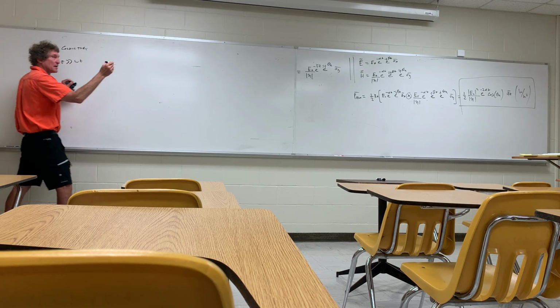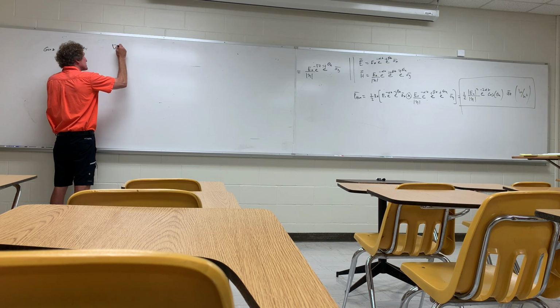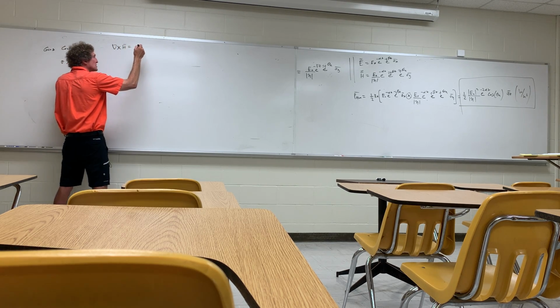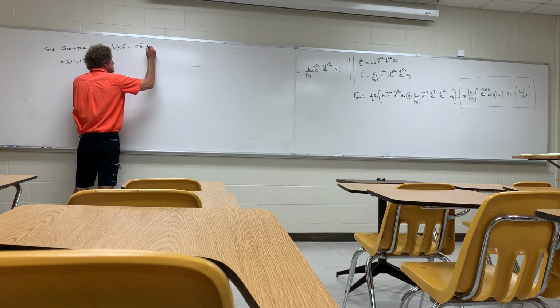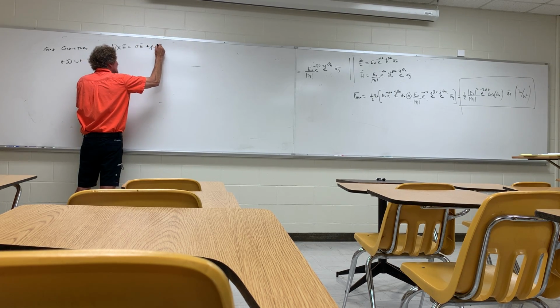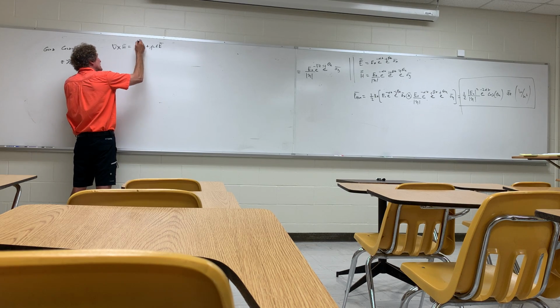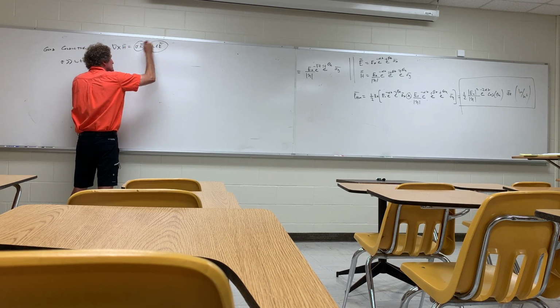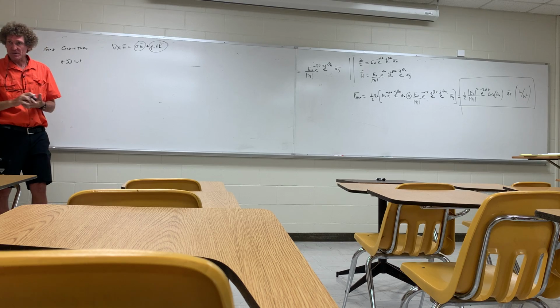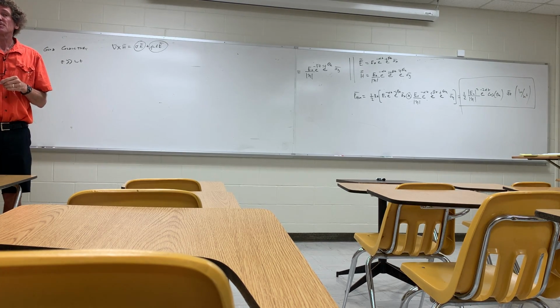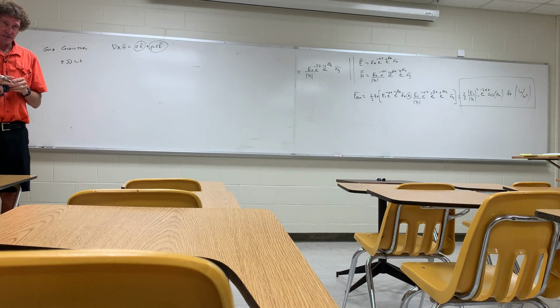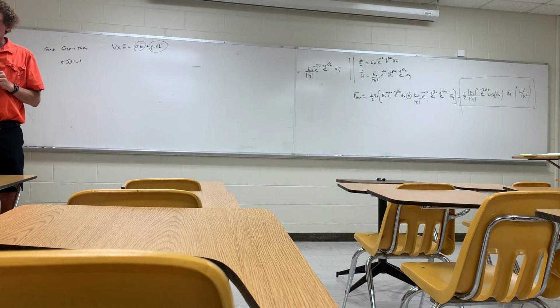And this is all about this equation: curl of H is equal to J, which is sigma E, plus j omega epsilon E. This is in the phasor domain. If sigma is much, much larger than omega epsilon, it's a good conductor. It means there's going to be a large real current density relative to displacement current density.